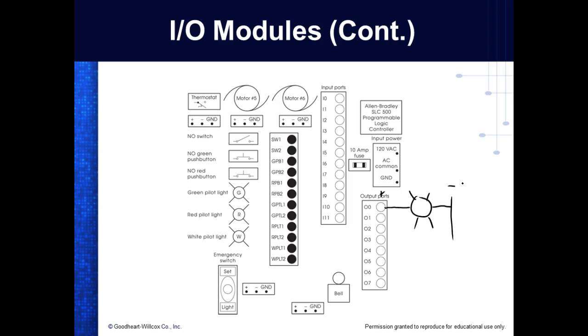So sourcing means plus. What do you think sinking means? So I would come over here and, at output 2, I might hook up a motor or a relay. Let's do it that way. And then I have to provide this, right? You understand that? So we'll have to run that out.